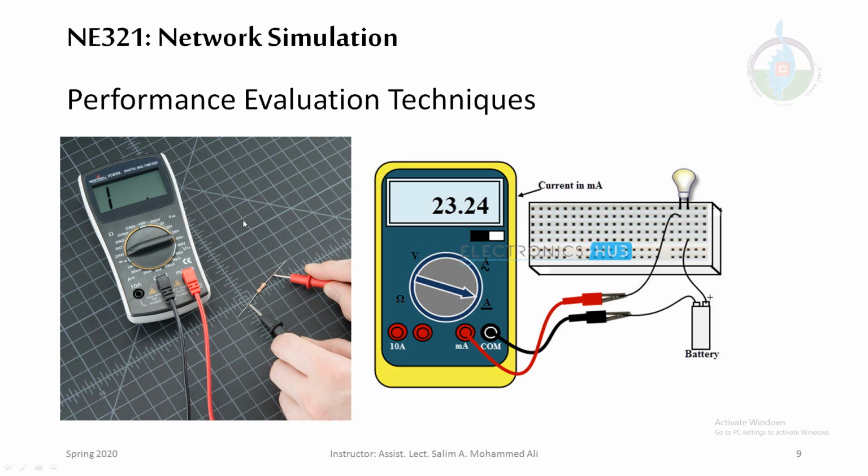But this resistor may be in a working circuit outdoors. The measurements will not be accurate because it has a different environment. So with sensitive systems, you have to take into account that maybe this resistor will operate at 80 degrees centigrade, not 20 degrees centigrade, and things may change as well.